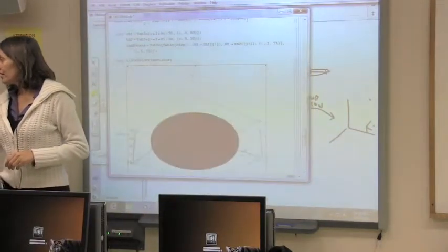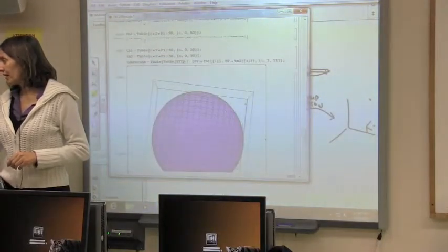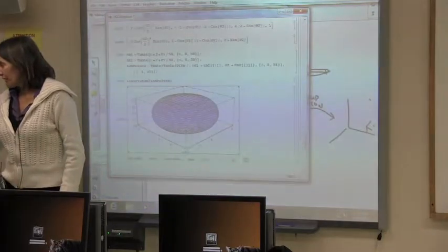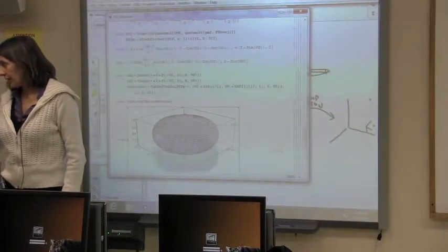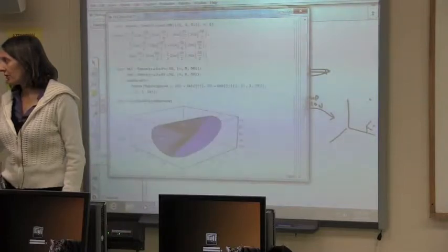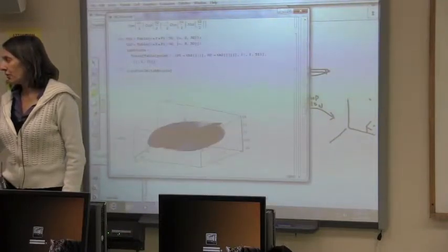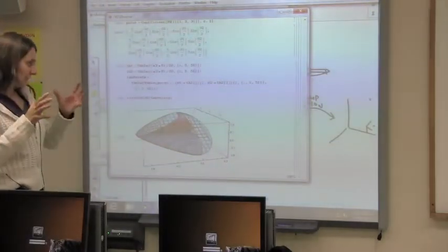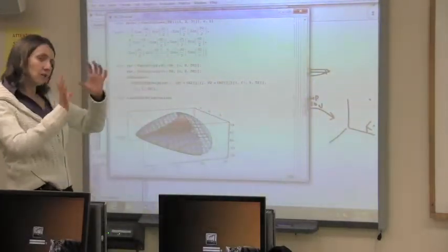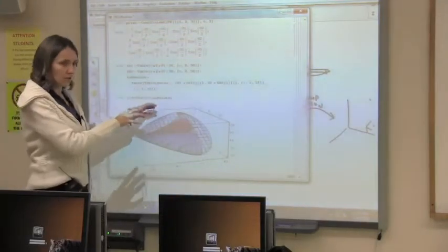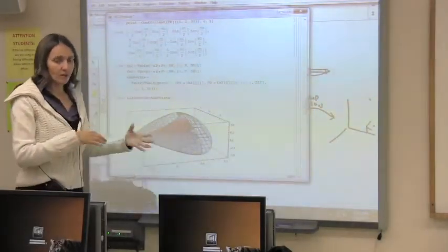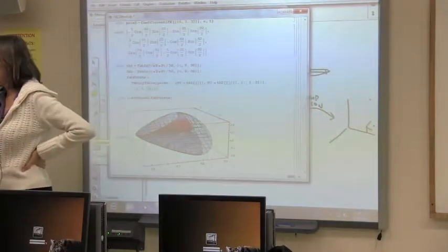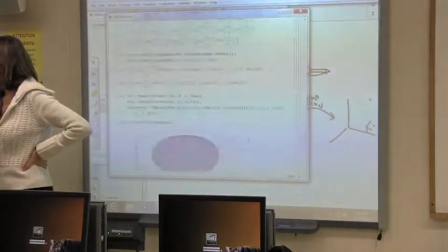So you see, this is the set of all possible points, more or less, up to the precision of this representation, that the center of the end effector can reach. These are 3 coordinates of your displacement. Imagine you take your 6-dimensional quadric, and you take just 3 of those components. It's like a projection of part of your quadric on the 3D space. And unfortunately, we cannot do better than this. So this is kind of useless, but the other one is good, right? The other one is useful.